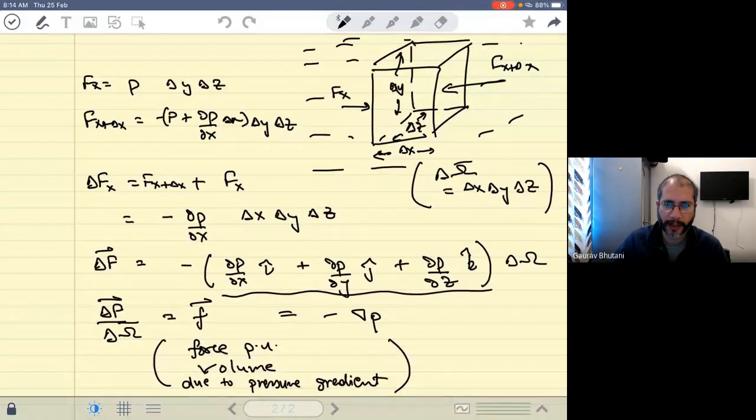So it's a very valid question that the cube is small enough so that when I go in the delta x direction, the planes we considered, the x planes, the pressure does not vary in the y or z direction on that plane. It's a very small cube. So I should have actually written a limit delta omega tending to 0. That is how we strictly should write it. In fact, I already had used dou, so we even could have written a df here. That could also have worked. But I mean, the ideas are, I think, clear.